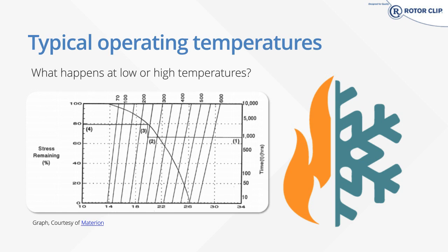You could go 50 degrees below, 50 degrees above. As you start increasing towards that 400 degrees, 300 degrees area, you start to lose performance, and then at 600 degrees, complete failure usually. So as you increase temperature, if you have a lower load, it's preferable.